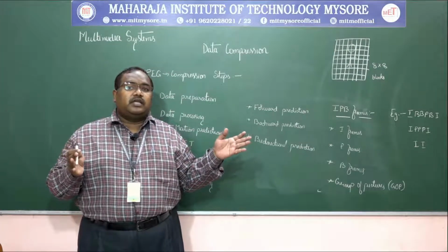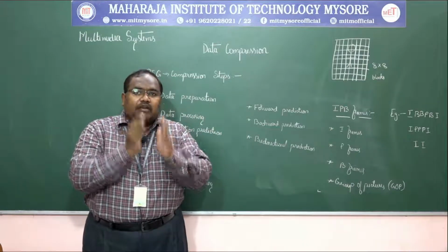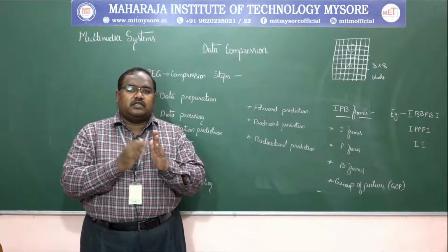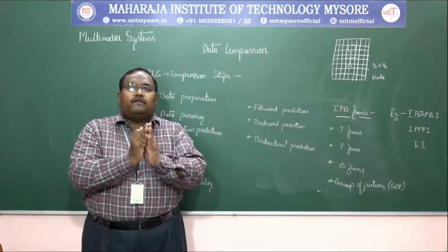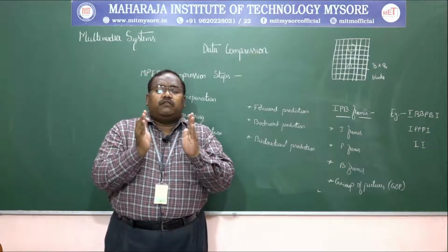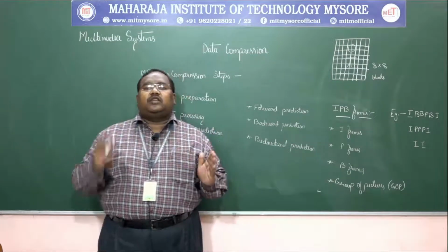So by using the quantization, we group it, because in the previous stage we have been retaining the lower frequency coefficient, that is DC coefficient. So we group those coefficients as one component. What is the meaning of that? The meaning of it is we are excluding the higher frequency range, that is the AC component.